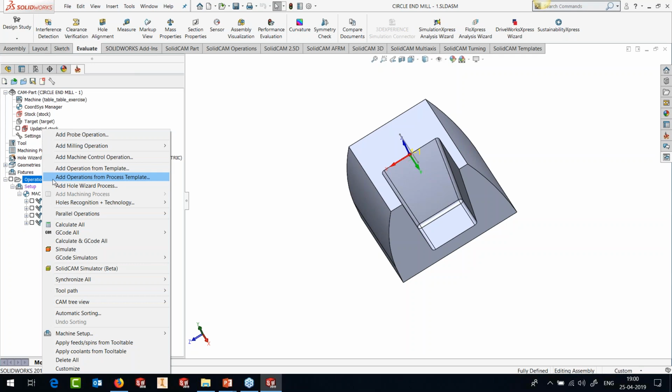The best part is that we do not exactly mirror the toolpath as it is, but the engine is so powerful that it actually mirrors the geometries that are used in the toolpath, and then it calculates the toolpath. So your climb milling on your part stays pure climb on your mirror toolpath. The direction of machining doesn't change. The direction remains the same. And that's the best part of this mirror.